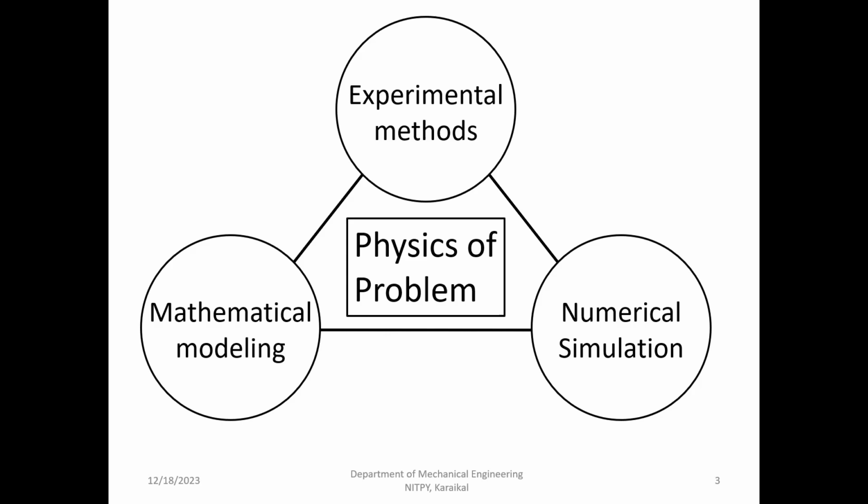A classical example is if we are looking at flow inside a pipe, and we say we are going to solve it with pressure and velocity terms alone, we are solving Bernoulli's equation. That means we have neglected the effect of friction. But when I take a pipe and do an experiment on it, if the pipe is not smooth, then friction effects will come into the picture. So that means my assumptions are wrong, so there should be an experiment to back it up.